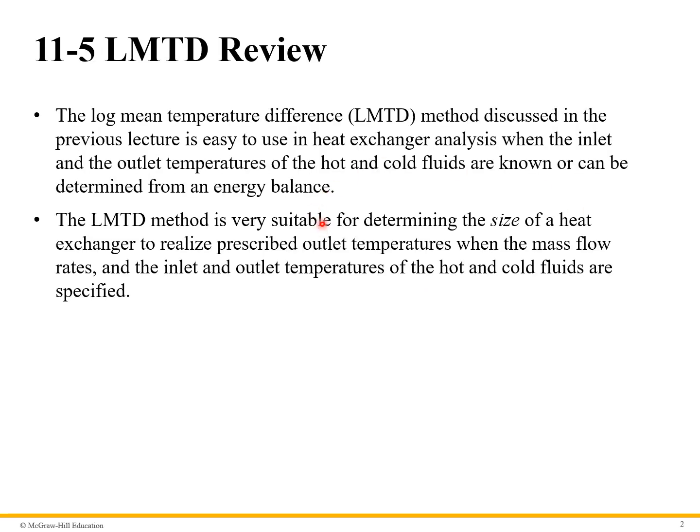Before we begin, let's review the log mean temperature difference method discussed in the previous lecture. This method is easy to use in heat exchanger analysis when the inlet and outlet temperatures of the hot and cold fluids are known or can be determined from an energy balance. The LMTD method is very suitable for determining the size of the heat exchanger to realize prescribed outlet temperatures when the mass flow rates and the inlet and outlet temperatures of the hot and cold fluids are specified.